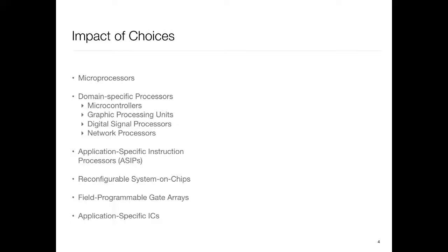Typically, on a single chip you will have a processor, perhaps an ARM core for example, surrounded by FPGAs, so sort of programmable wiring and gates. Then you can take your design, figure out this goes to software, this goes to hardware, partition it, the FPGA handles the part which goes into hardware, and the rest goes to software.